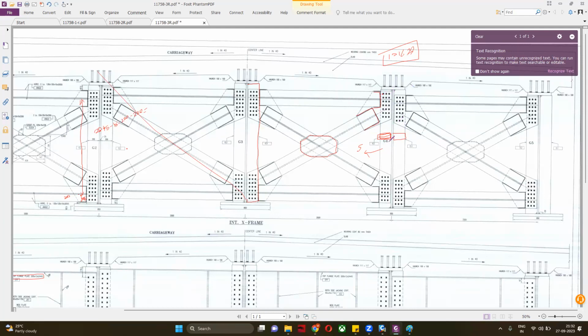How will this system be, sir? How will buckling happen? It will buckle like this. This stiffener will first try to resist this buckling, but it will resist at the middle. Maybe it will create more buckling in this stiffener also, and in the web as well. The stiffener will resist a little, very little. But due to this, our stiffener will also try to buckle.